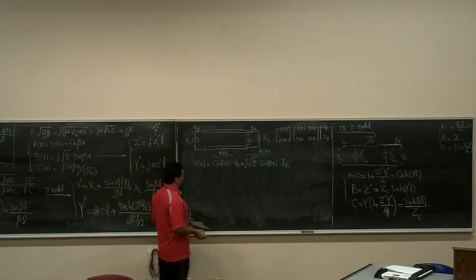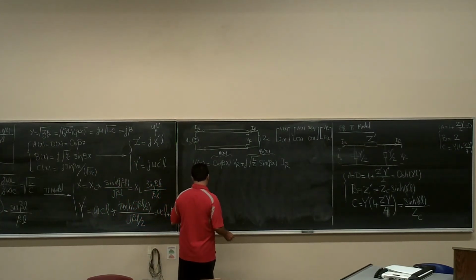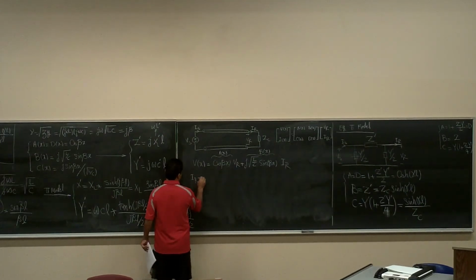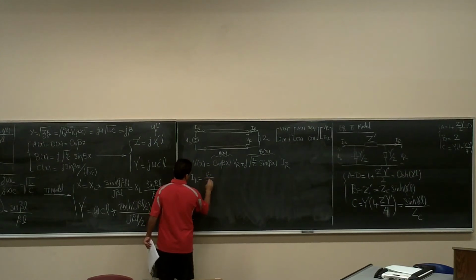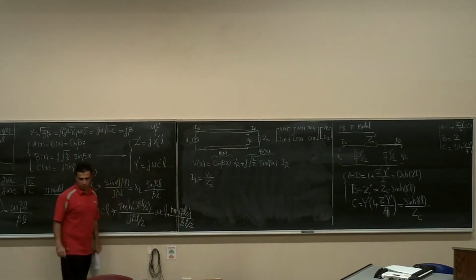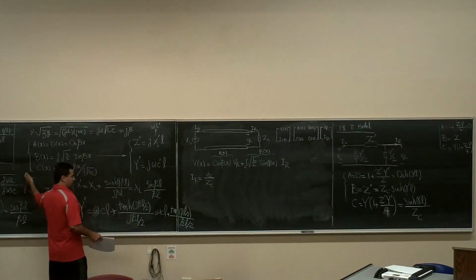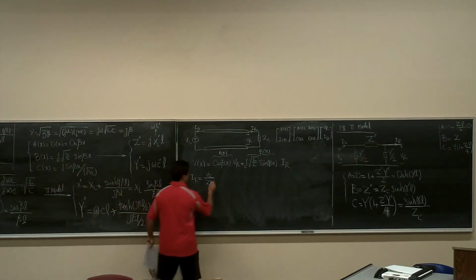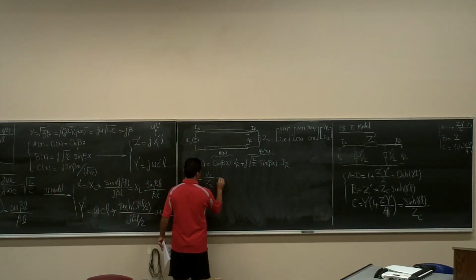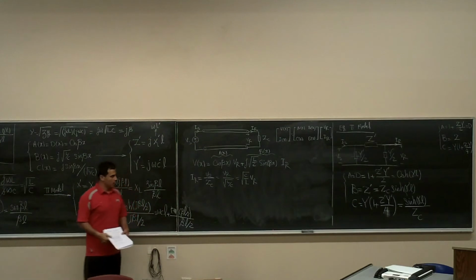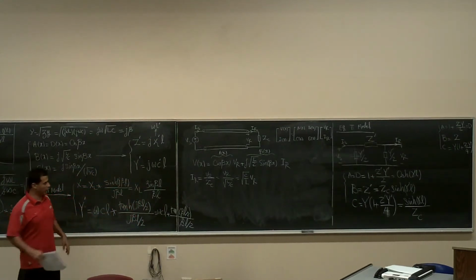So let's simplify this one. IR, I can replace it with what? I can say IR is equal to VR over ZC, right? And what is ZC? It's the square root of L over C. Basically, it's going to be VR over the square root of L over C, or square root of C over L times VR. Now let's replace IR over there.